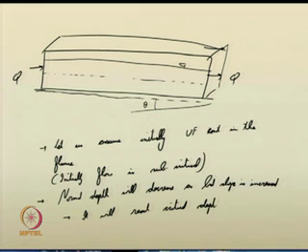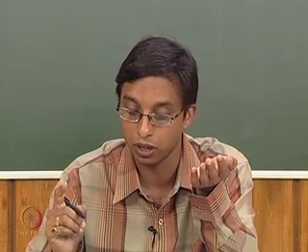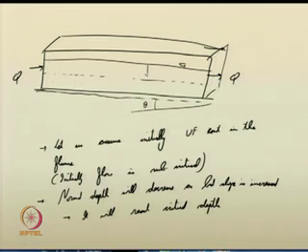critical depth. So, for the given discharge in that uniform flow channel, when you raise the bed, you have seen that the normal depth is decreasing and it will reach the critical depth in that channel. So, that particular critical depth, whatever depth of the flow is abiding the critical flow condition, has been achieved for a particular slope of the bed.